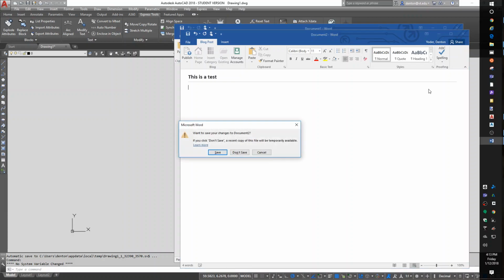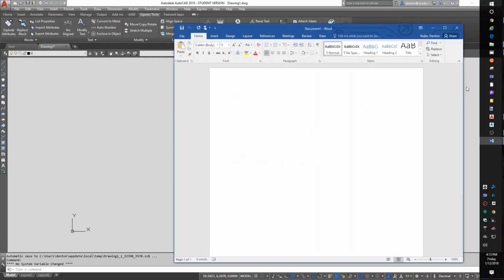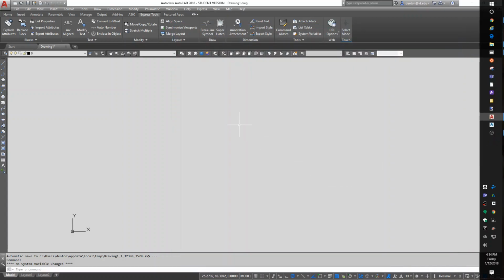In AutoCAD, it's even more used. So if I start a new drawing, I get a blank drawing, right? Okay, well, what are the settings? Any drawing setting, any setting that is stored in the drawing can be saved in the template file. So when you start a new drawing with that template, you get those settings. Examples of good uses of that.